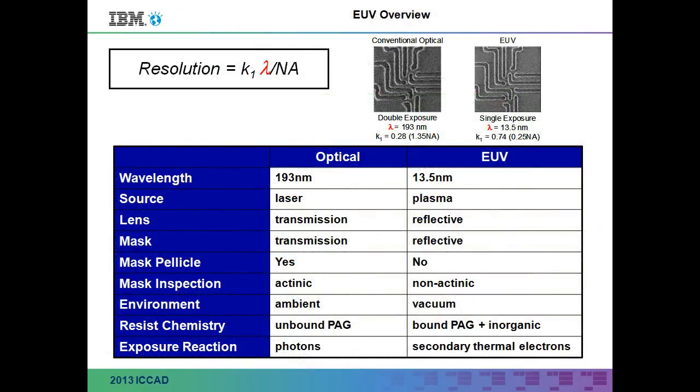So, a quick update on that, just to convince you that it might be a good idea to at least keep looking at some of these issues on the back burner. EUV gets this resolution by going to a much shorter wavelength. We go from 193 down to 13.5, that's called 14 nanometers. It gives you a much better image. The problem is it's all reflective optics, so the numerical aperture is significantly smaller. The initial tools are 0.25, now we're going up to 0.33 numerical aperture.